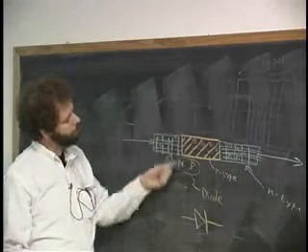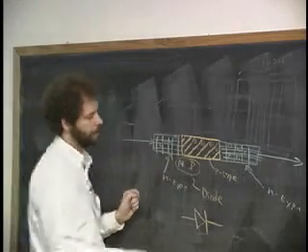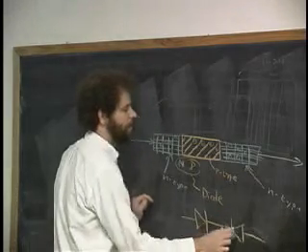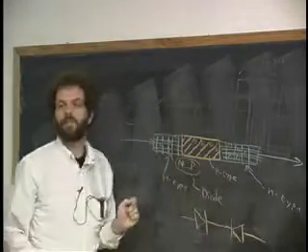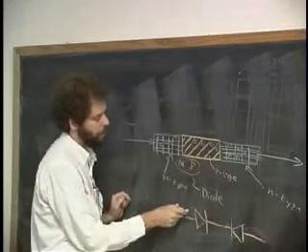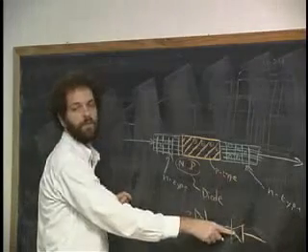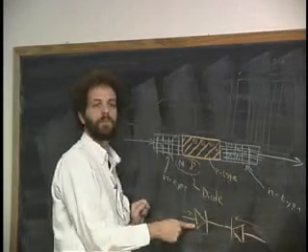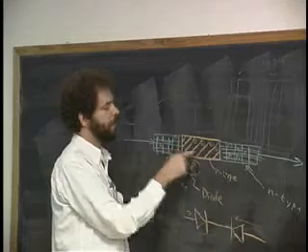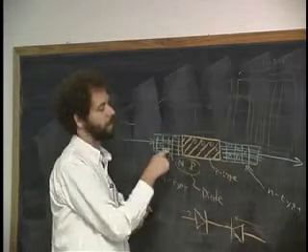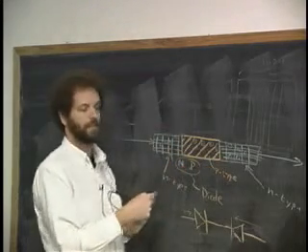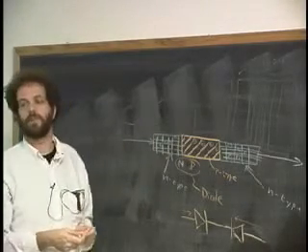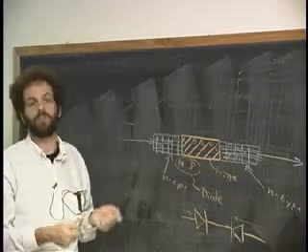And if you'll notice, the structure over here is such that there are two diodes, each pointing towards each other, like this, towards the middle. So if I try to pass current through this way, it'll get through this one, but it won't get through that one. And if I try to pass current through the other way, it'll get through this one, but it won't get through that one. So this NPN structure, and you could also build it PNP, it doesn't actually make any difference, is a structure that does not let current go through. It functions as an insulator, an open switch to current.